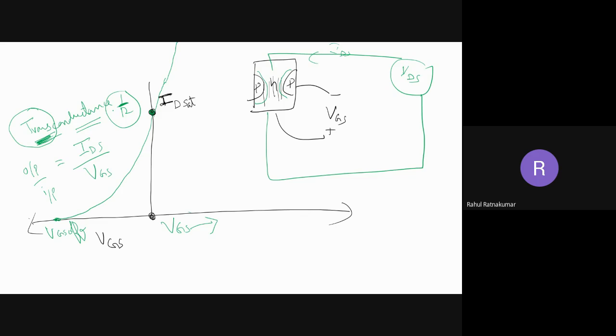It is not transresistance, it is transconductance. We take the dimensions of current divided by voltage, so we have I divided by VGS. This is called the transconductance curve, which we have drawn here, just to understand the term. Transconductance is usually represented by gm.